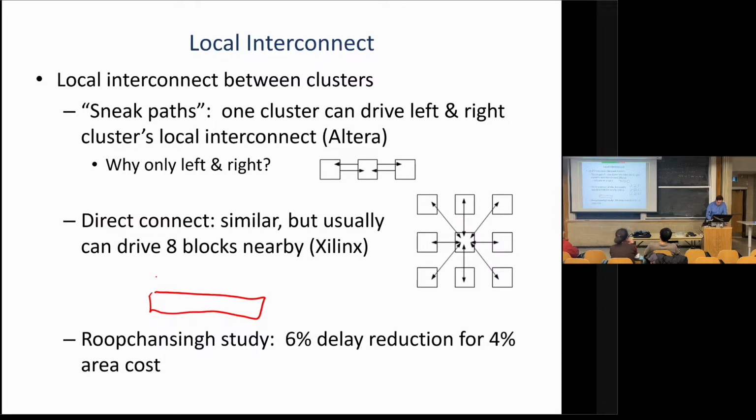So what Altera does is when you buy, so if you buy a chip that has 100 rows of logic, that's what you can see in Quartus, it'll really have 104, okay? And that means that you can have up to 4 broken rows and still sell that chip. And that increases yield a lot.